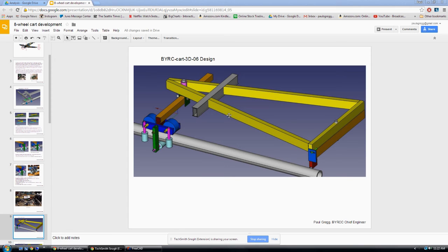It's stiffer and stronger when it's standing up. And so it did get a little tall. These members here, I don't think I ended up doing this, but if you're going to cross members in the same plane, in the same space, the member that's holding the higher load, the more critical member, should have the right of way through here.